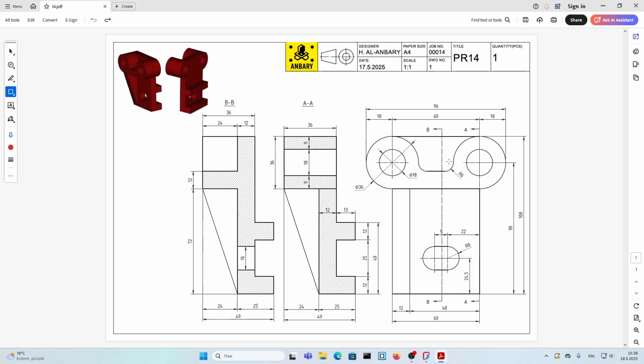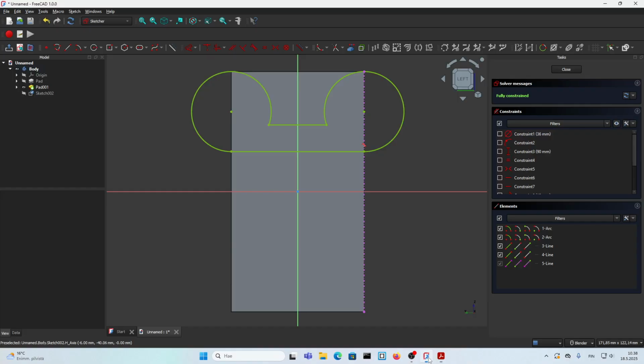Now you saw in the drawing I have a fillet in here. These fillets, I can make them onto the 3D model, but making them onto the 3D model may cause problems. So to avoid problems, I would suggest that you would always try to make these fillets onto the sketch. I think it's better. So fillet tool,